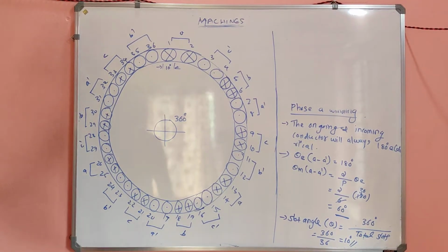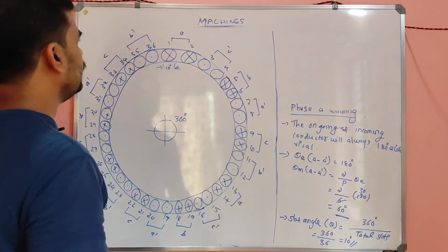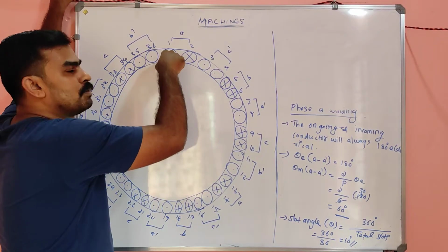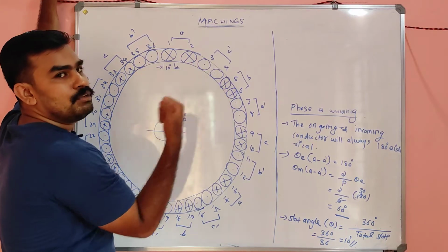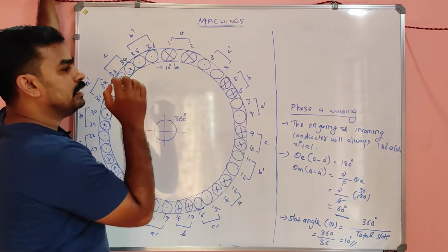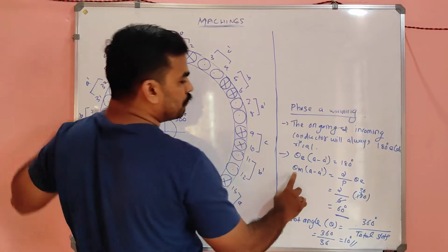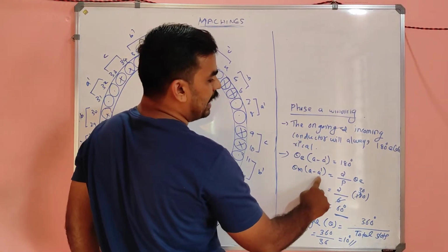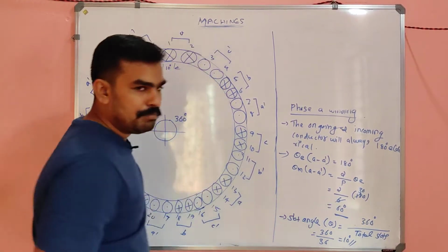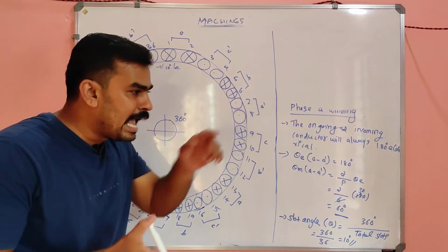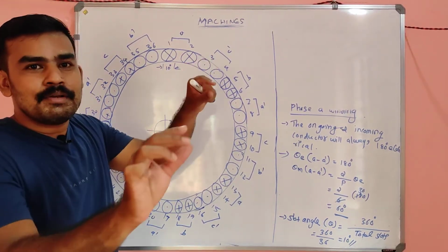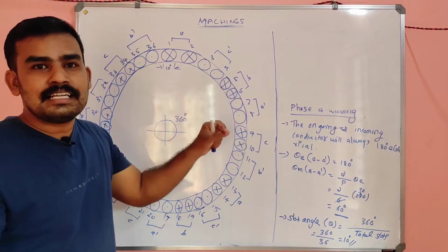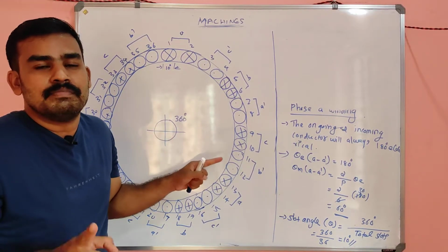Okay, listen my dears. From slot number 1 we inserted phase winding A. The meaning of theta mechanical degree between A and A dash being 60 degree is that this much angle is subtended by these two windings.